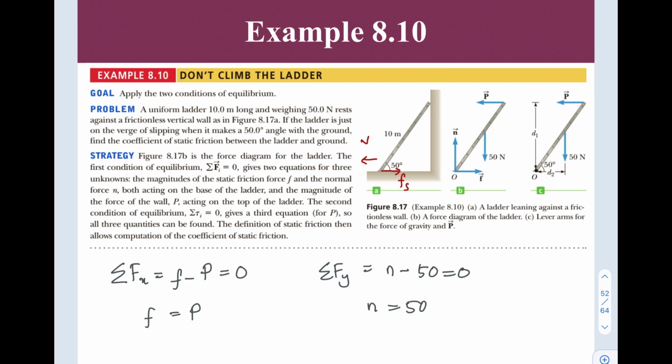So from here we have the free body diagram. Now, the point that has many unknowns, which are the normal and friction, is point O. So it is the best point to become our pivot. It is not stated here, so it is up to us to choose which point to be the pivot.